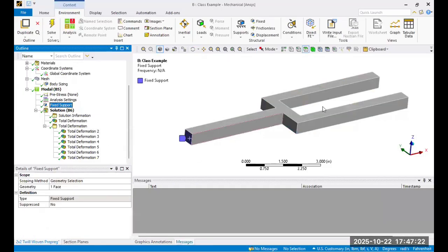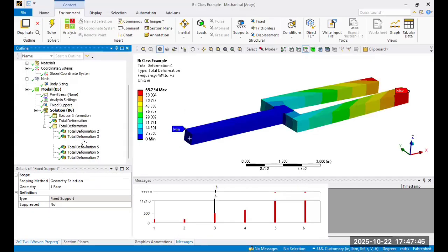And also the same thing is, like the professor said, if you make it longer, what are you actually doing to your geometry? Sure, the Young's modulus, the material is the same, but the stiffness is changing, right? The bending stiffness of your part is changing, and your bending stiffness is lower. And so if frequency is proportional to root of E over M, because the actual stiffness is now lower, you're going to be seeing lower frequencies.